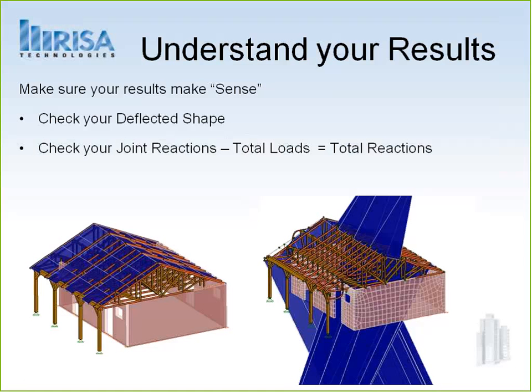We actually have a nice big warning message that pops up in RISA-3D that went in about a version ago, that if things are getting lost, things are going into a locked node, or if there's any load loss, we're giving you a big, big warning, okay? But this is something you should also manually check. And then understand the code check. So if I get something that gives me under 1.0, I should check it, not just take the computer program's idea for that, right?